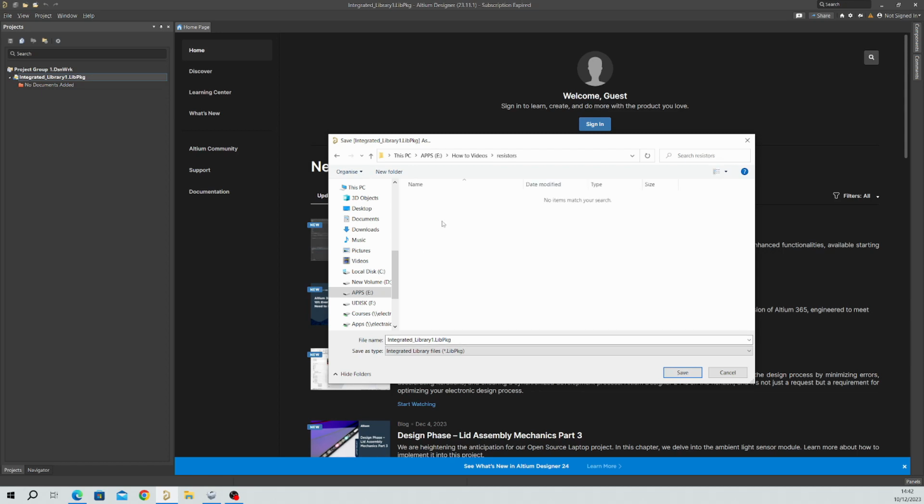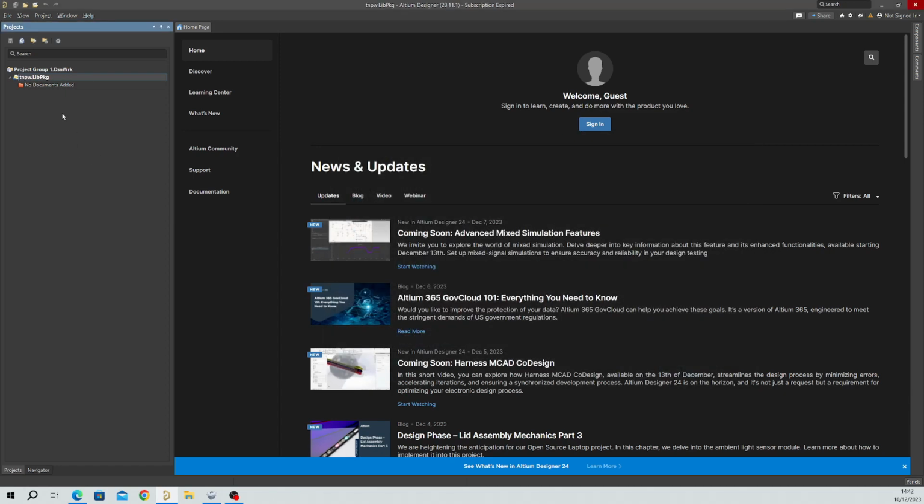Okay. So what we'll do, we'll save this as a TNPW. The TNPWs are a type of resistor which I tend to use. They are 0.1%. We can get them in different percentages, but I generally use them for precision work. 0.1%, 10 or 25 ppm you can get.